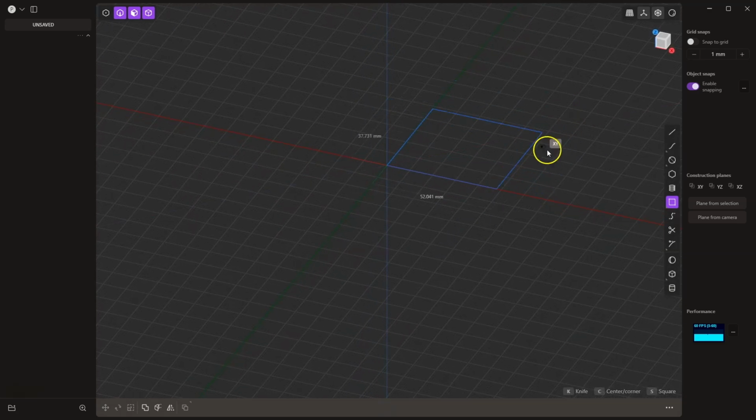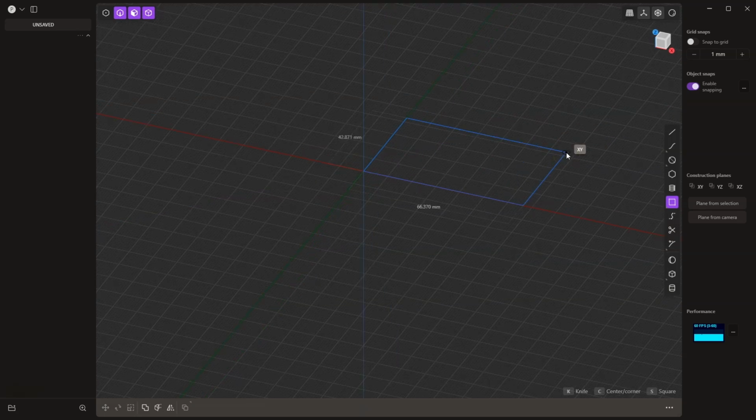And so, here I have the drawing of the rectangle, and while drawing this rectangle, we see what dimensions this rectangle will have. A helper line has also appeared. This means that if this line is active and we draw the rectangle in such a way, we will create a square, that is, the sides of the rectangle will be equal. But if we want to specify precise dimensions for the geometry, we need to press the Tab key. I press the Tab key and I can enter a specific length for this side, for example 100 millimeters.